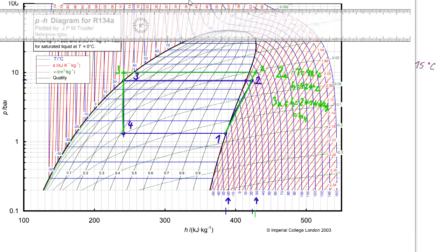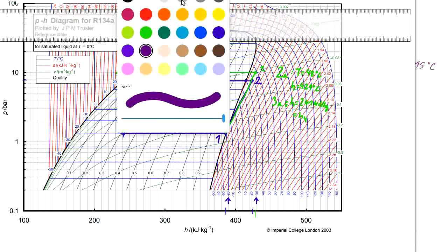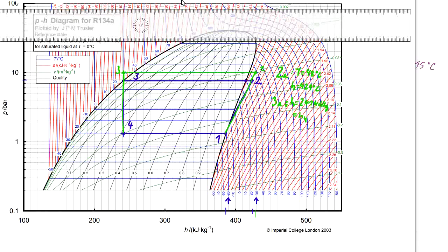So we have the evaporation pressure for minus 20, but we will go into the slightly superheated vapor, so at the same pressure, but to the temperature of minus 15. So in purple, the point 1 would be over here, and the enthalpy seems to be right above 490, so let's say 491 kilojoules per kilogram.